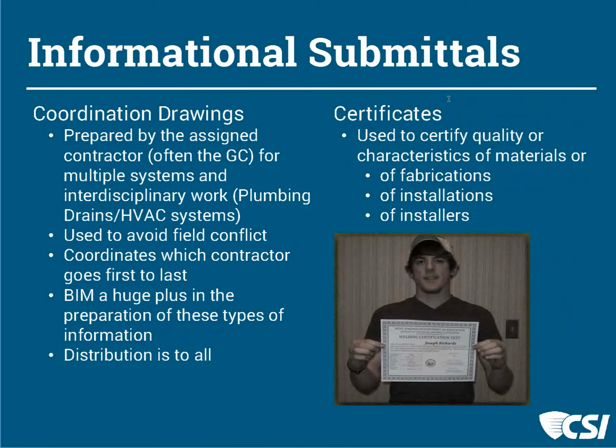Now, having said that, I can tell you that on many jobs that I have been associated with, the coordination drawings were done almost as an as-built record, or as-constructed record, as the work went along, and they were not at all the coordination drawings that we were hoping to see. Folks were coordinating as they went, and I think that has hurt the projects where that was allowed to happen.